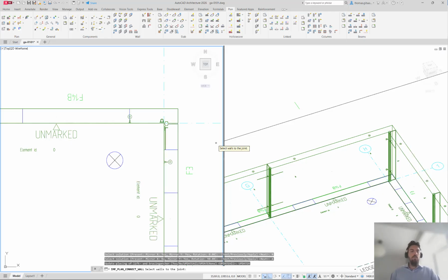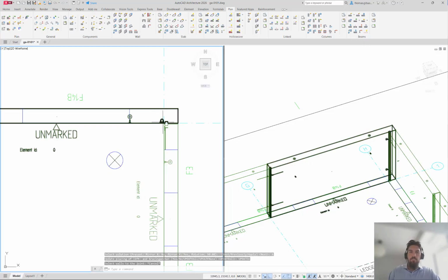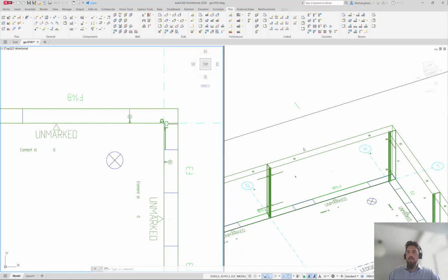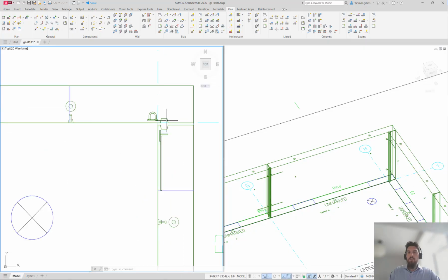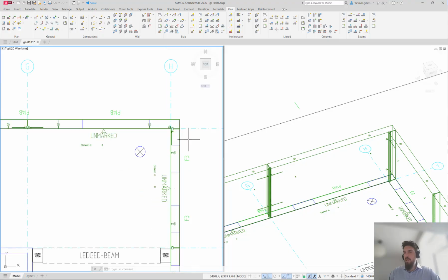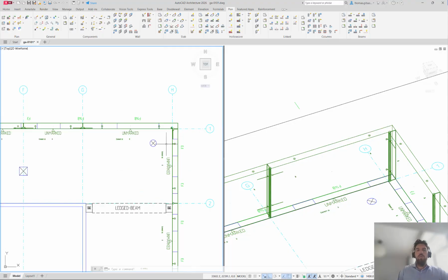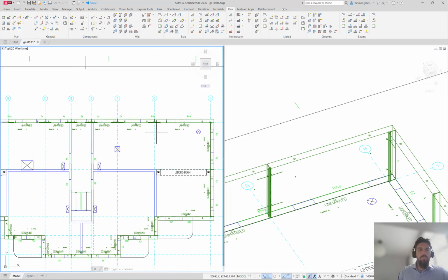So you see here how the software recognized by itself very quickly, changed the custom material in the edge, made this wall bigger, made this shorter, and made the connection with, of course, the 20 millimeter distance that I have decided should be the distance between my walls.